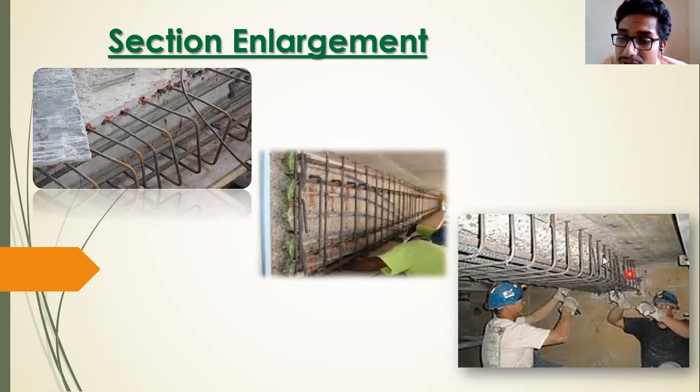From this picture, I want to tell you something. When you are going to do some repair work, undercut is very, very important. If you do some patching work, you should not just remove the top surface of the concrete, do some cleaning and patch. No, we have to remove the entire contaminated concrete.